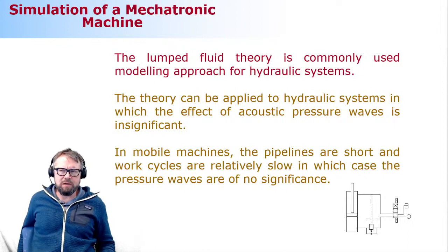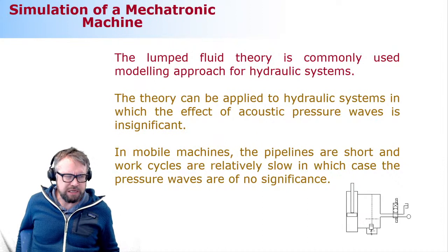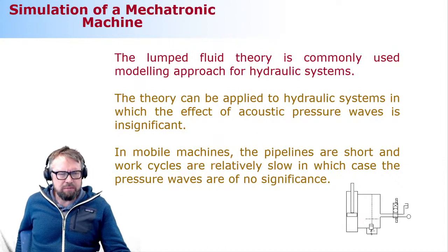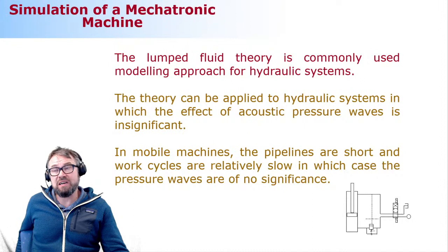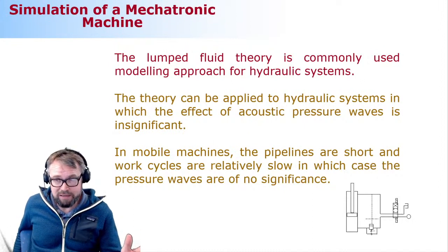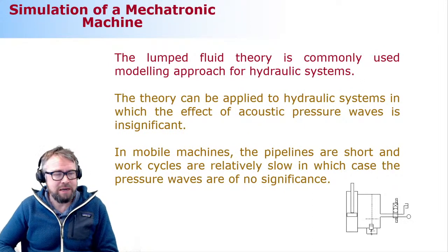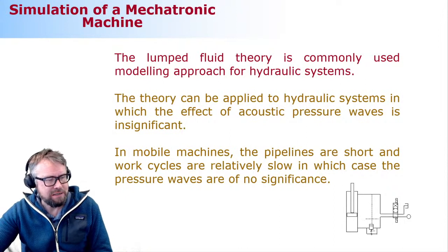In industrial applications it could be a bit more significant drawback. But in mobile machinery, pipelines are fairly short and work cycles are relatively slow, so these pressure waves are typically not a big problem. If they are a problem, you cannot tackle them using this modeling technique.